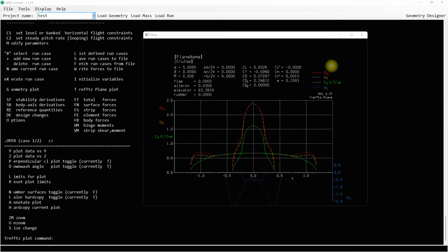So if I go back, I see that my angle of attack is right now at 5 degrees. The CL amount I have is 0.8, so it's a good amount of CL. And I also see that none of my CL is going to the amount or the angle of attack that it would be stalling. We want to keep all the CL below the stalling point. So what we see here is that the stalling can happen if we have at these sections of the airfoil